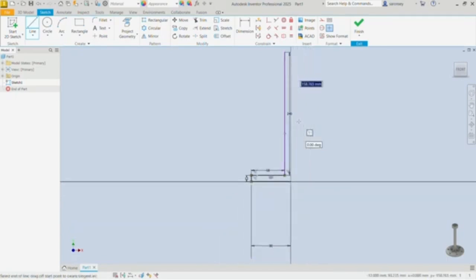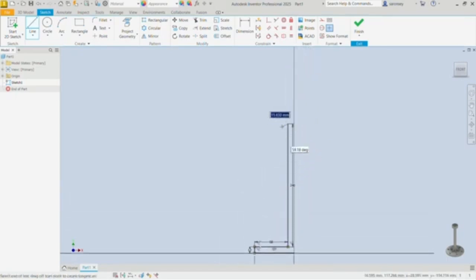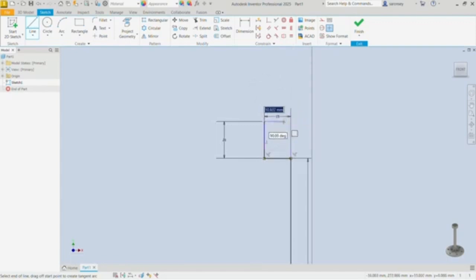Double click the scroll mouse button and even pan down also. Now we'll move perpendicular to that to the left to a distance of 15. Let's enter that. Let's go up perpendicular to a distance of 20. We would enter that. Now to a distance here of, let's do 8 and enter that. Now we'll come down perpendicular to a distance of 11. We can enter that as well.